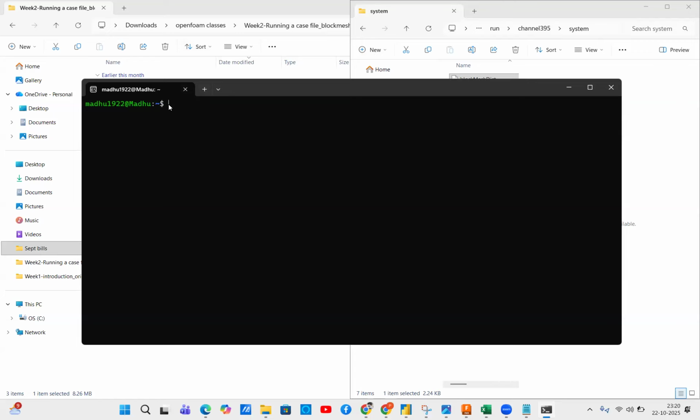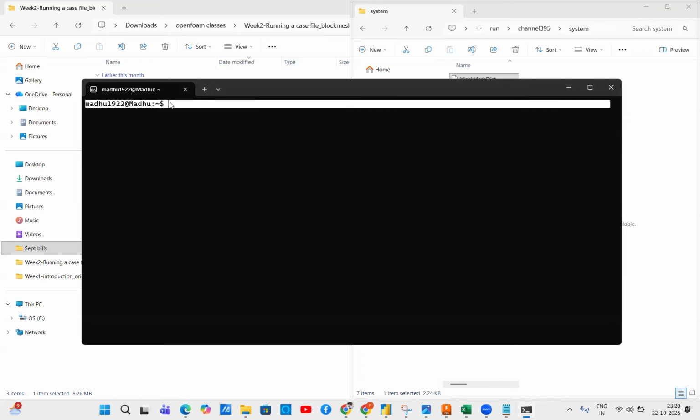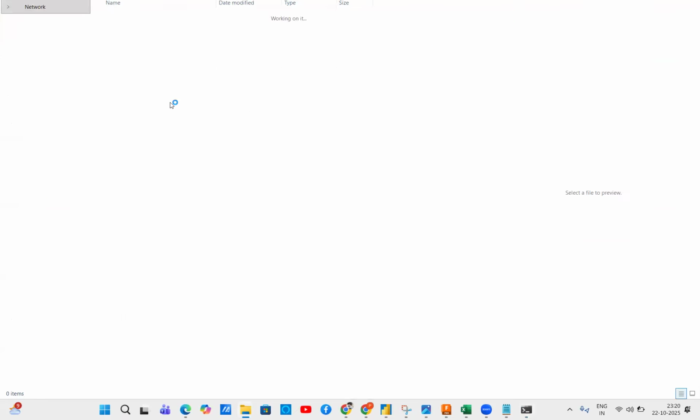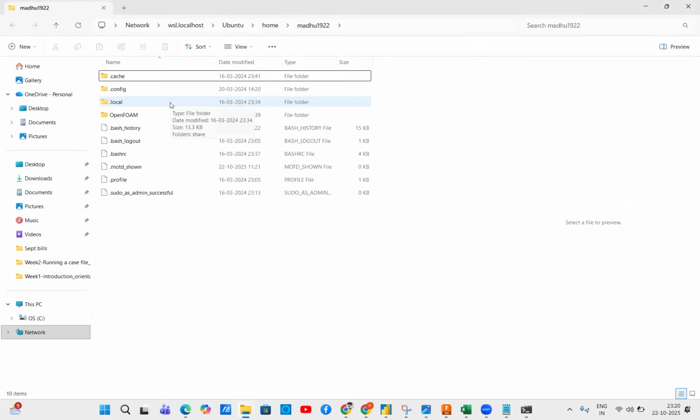Basically, what we did is air residence time. We calculated how much time air can stay. We modeled the washroom in the train in AutoCAD, exported the file from AutoCAD to OpenFOAM, and created a solver for calculating the air residence time. Till now, we have the solvers for calculating the velocity, pressure, and temperature.